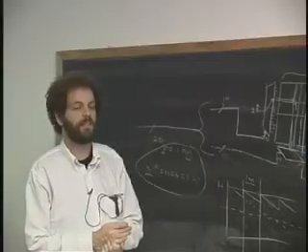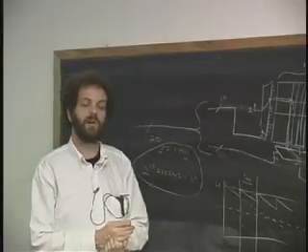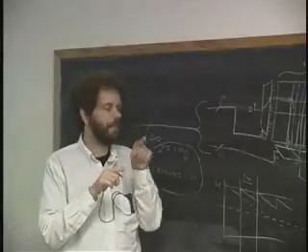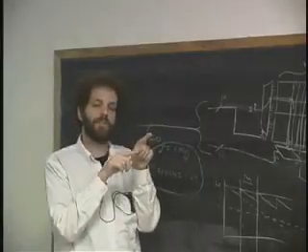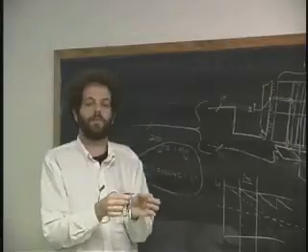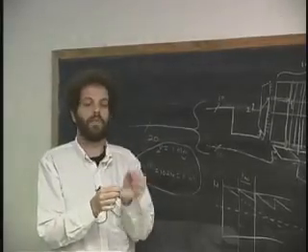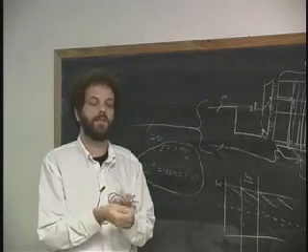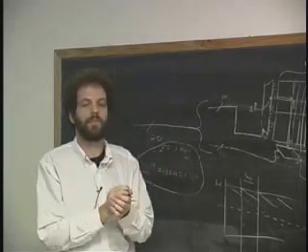Sometimes, in fact, in the old days, this problem was so hard that they wasted half of the lines. Whenever they had high charge in one, they'd put low charge in the other. They'd suck down on both of them and look for the difference. So whatever effect happened to one would happen on the other. You throw away half the bits, but you sense what the difference was between one and the other.